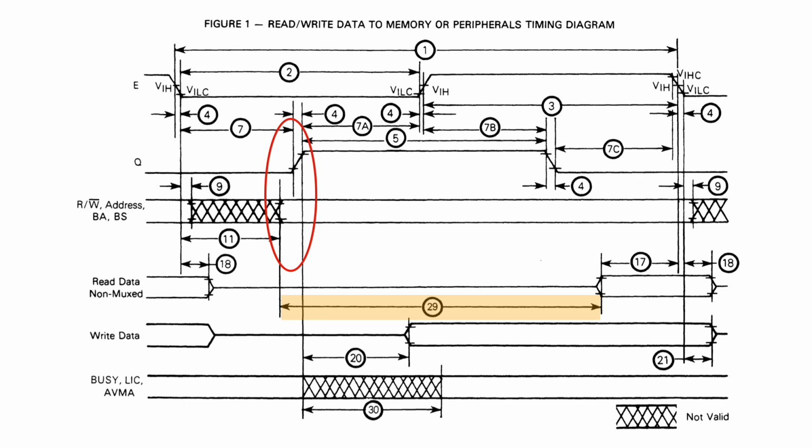Now, I also will be buffering the CPU's address and data buses with 74AHCT245 bus transceivers, which themselves have a typical propagation delay of 9.5 nanoseconds. There's actually a good reason to do this though. Not only does it overcome the 6809's relatively low fan-out capability, but it also effectively converts the TTL logic level outputs on the 6809 to 5-volt CMOS logic level outputs, which means that I have a wider selection of components available for use in the rest of the system.